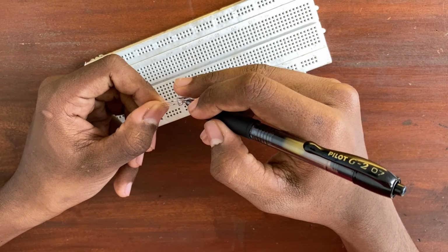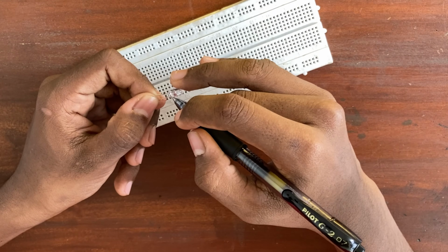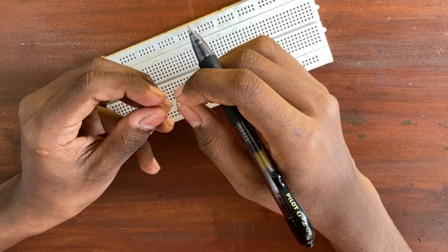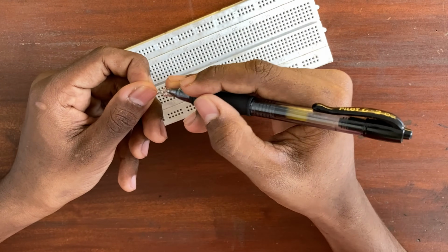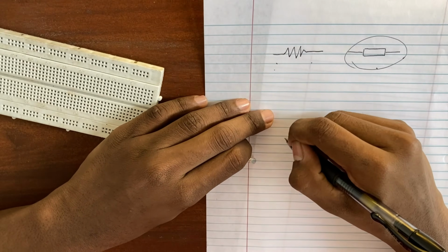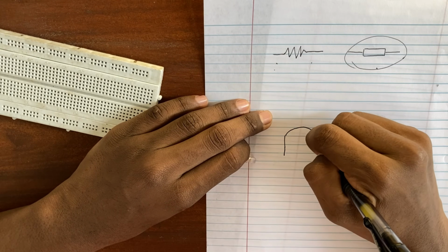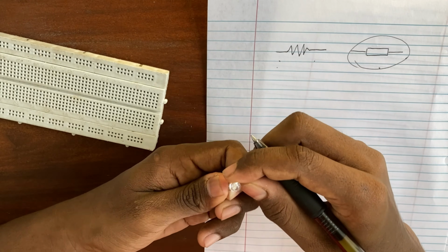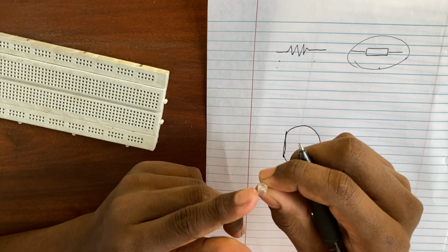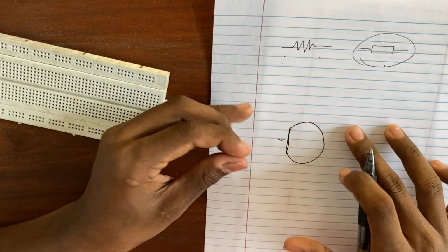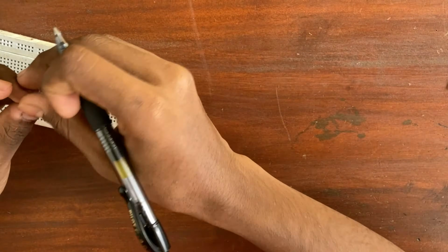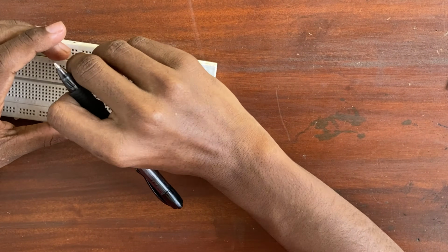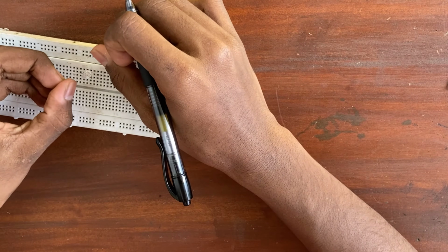In a transparent LED there is a bigger part and a small part inside. The small part is the positive side and the bigger part is the negative side. And there is another method to identify it. There is a little notch here like this, a little cutout here. You will feel it. It's the negative side, the minus.